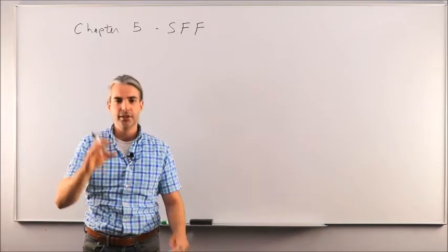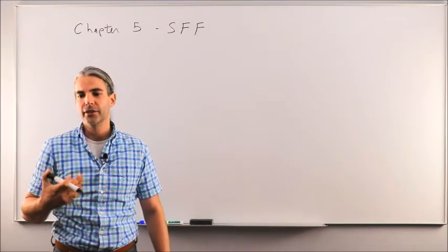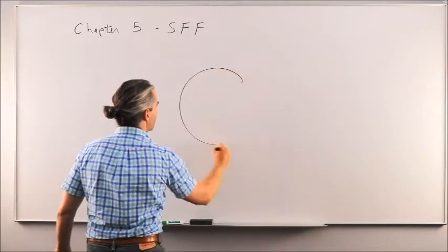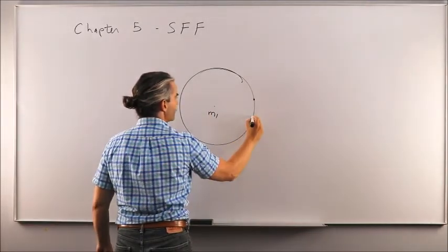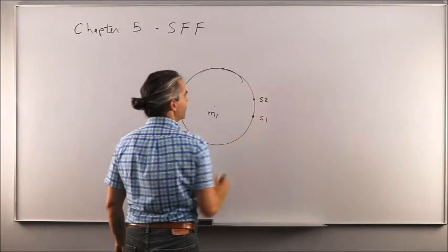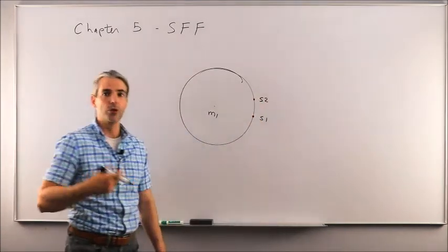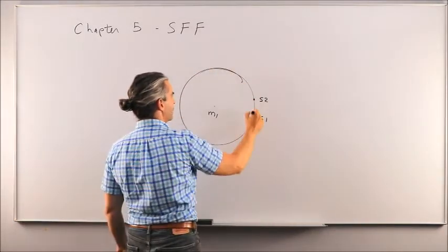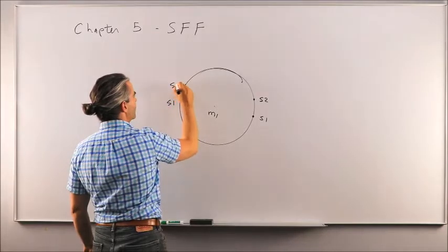So if you look at section 5.1 in the lecture note, which is titled Relative Orbit Geometry, there are no equations. This is just a very simple blurb about the historical perspective of formation flying and about the fact that in its simplest form, formation flying would consist of two spacecraft along the same circular orbit, like that. Spacecraft 1, spacecraft 2, such that the angular separation between both spacecraft would remain constant as both spacecraft evolve along the same orbit, okay? So the separation between both spacecraft will always be the same because they're both traveling at